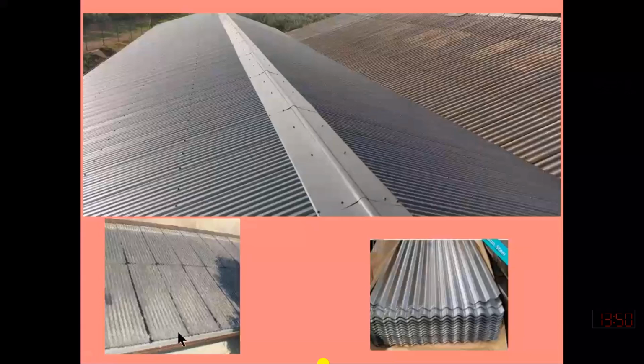So it means that if the inclined length between the purlins is more than 4 meter, then we need to use another purlin within the span. We cannot cover the spacing between two purlins if the inclined distance is more than 4 meter. So at the start, we practice making sure that the total inclined length between panel points should be less than 4 meter. And how we will do that, I will explain.